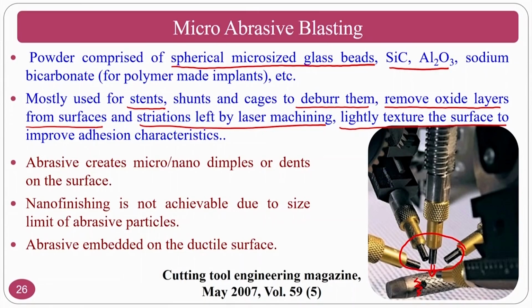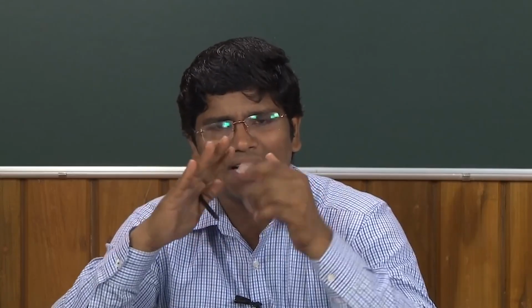So these abrasives create micro-nano dimples or dents on the surface. Normally for bio applications like stents and other things, you require a super hydrophilic surface, because you need cell attachment, so the artery can attach properly on the top surface of these coronary stents.